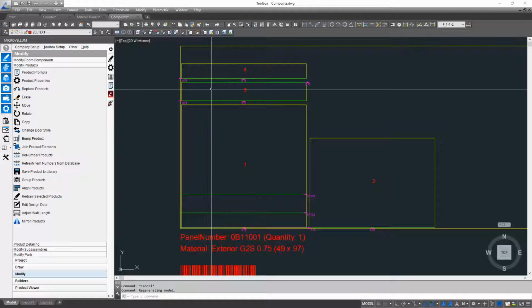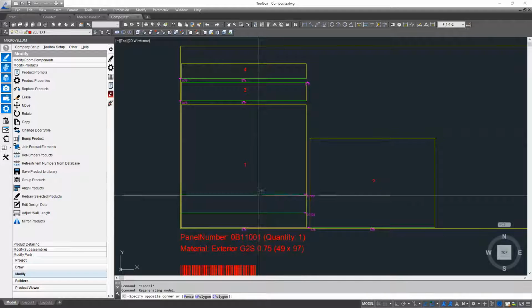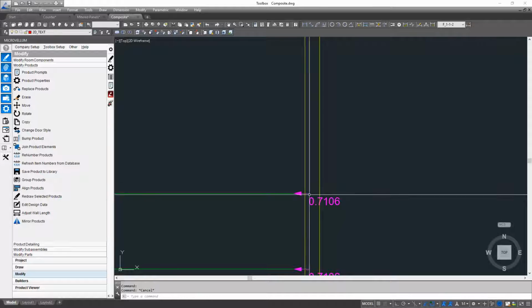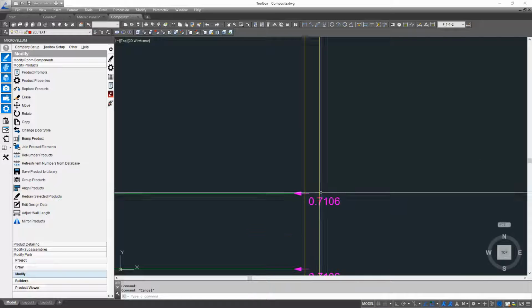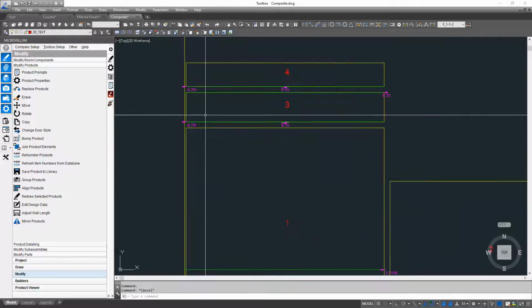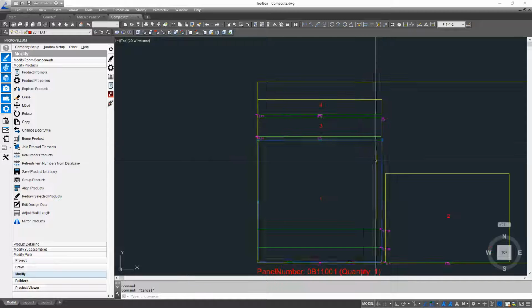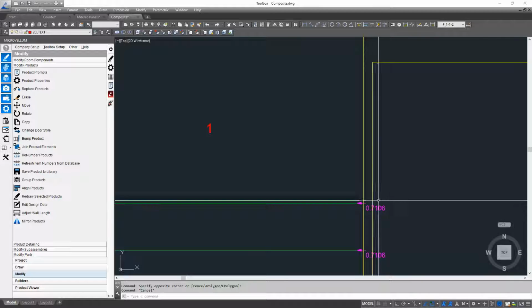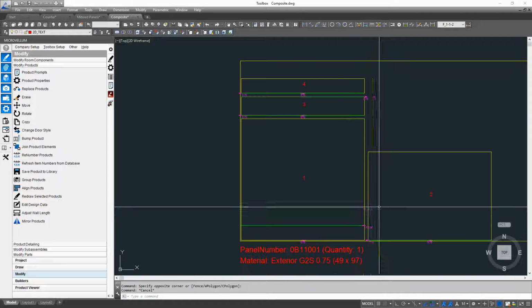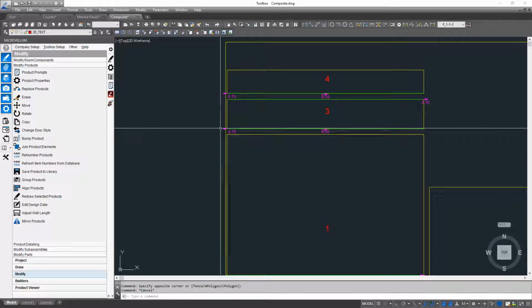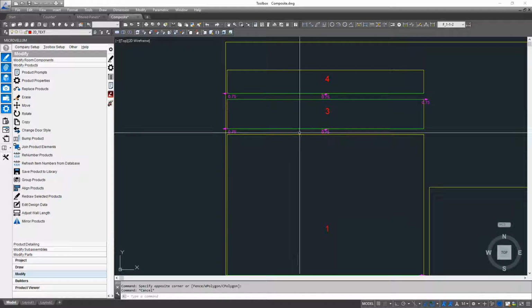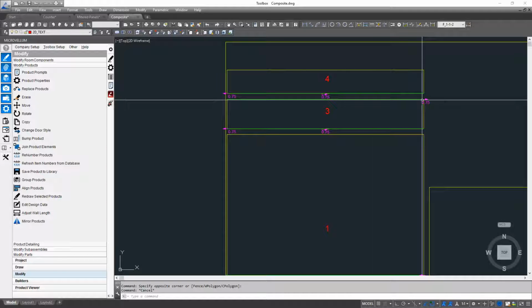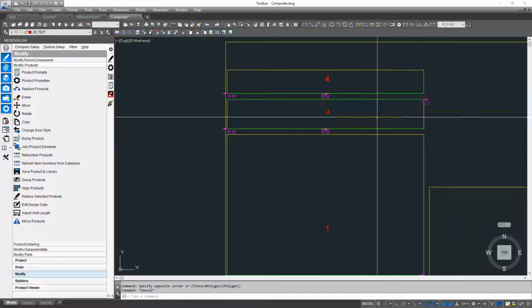And so here in my nest you can see the machining for that part, and so there's my routing for that routing operation. And so if I bring in my tool there, I just need to make sure that it's not going to damage that part and adjust my spacing between parts accordingly. And so this is the miter fold part, right? So that's one part that's machining part of the way into the material and leaving a bit at the bottom. And then these are my individual miter parts, and they're going to cut all the way through the material right down to the spoil board. And those come through with the machining for the individual parts there.